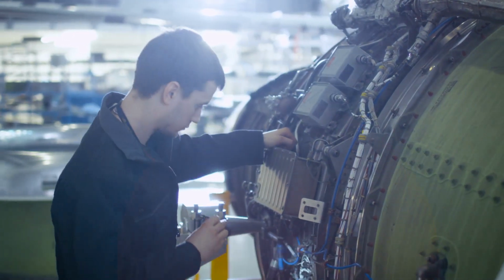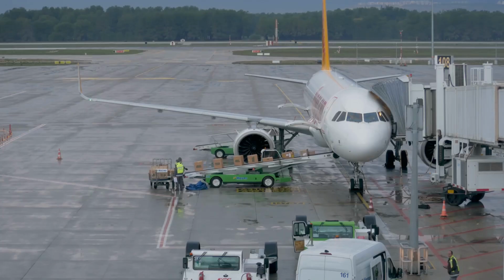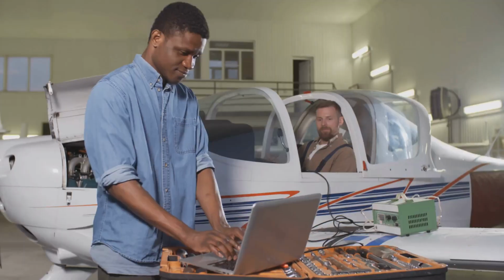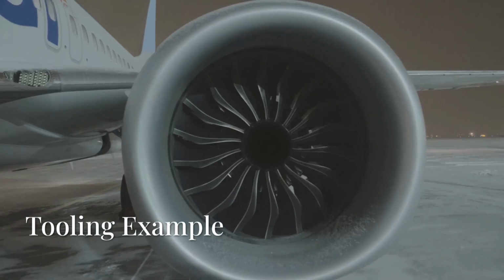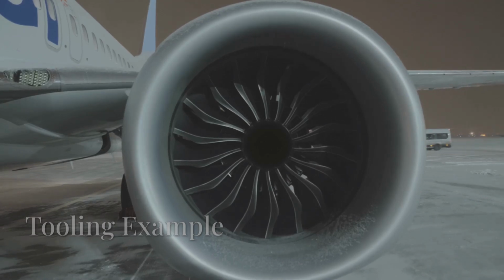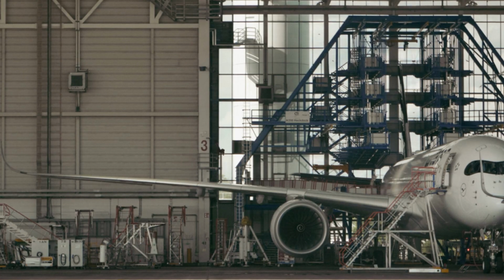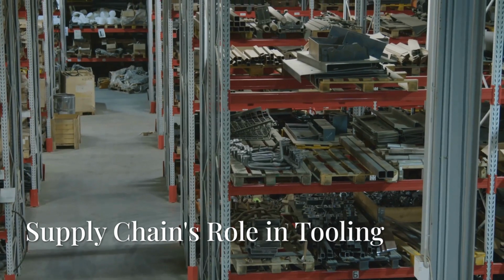Maintenance requires more than just parts. You also need specialized tooling and GSE or ground support equipment. This includes things like engine stands, hydraulic testers, calibration rigs, jacks and safety gear. For example, a CFM56 engine needs a specialized sling and cradle to be removed safely. If it's not available, the entire maintenance job is, well, delayed.